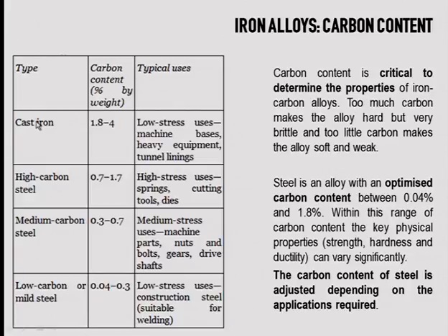To determine the properties, generally you could say, why don't I add the maximum percentage I can of carbon so that I get a very hard material? But at the same time you increase the possibility of the material to snap. It becomes very brittle and almost impossible to weld. So that's why in the 19th century most of the buildings done out of steel were done with rivets, because it was difficult to weld them, because they used either wrought iron or cast iron.